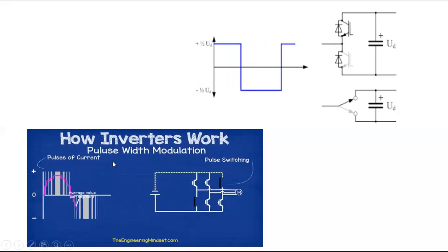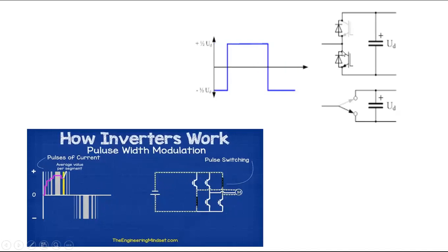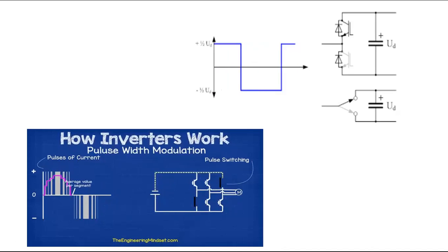So what type of signal does the inverter generate? It is a modified sine wave. How this modified sine wave is created is also one topic. But as it is an introduction, I want to show you the bridge inverter is the inverter used everywhere. The H bridge inverter circuit we will study. That H bridge inverter first generates the square waveform, which is also AC, and then it is modified to a modified sine wave.